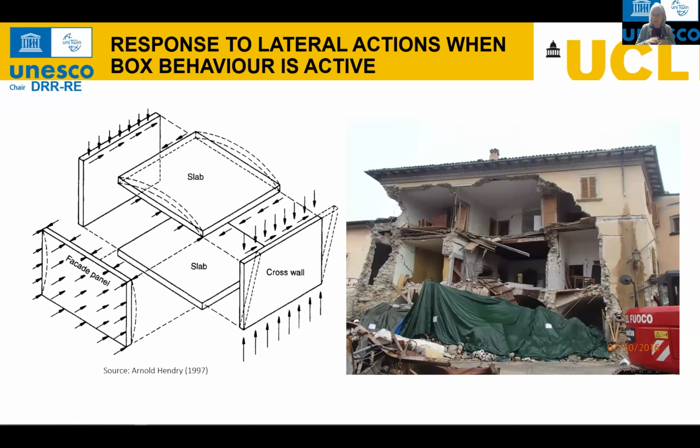The roof is still in place, but the facade might have collapsed. So it's not sufficient to think about a rigid wall or a rigid roof, but we need to think about the relative stiffness of all the parts and how they can work together without concentrating failures at particular points.